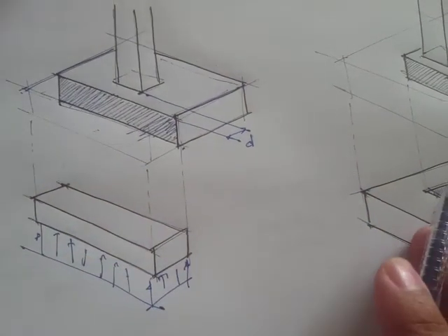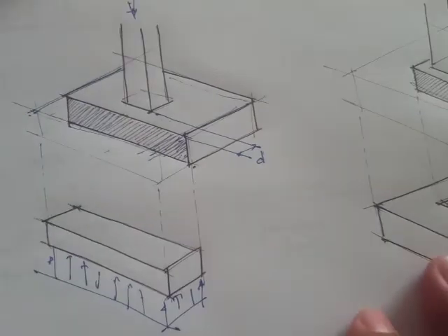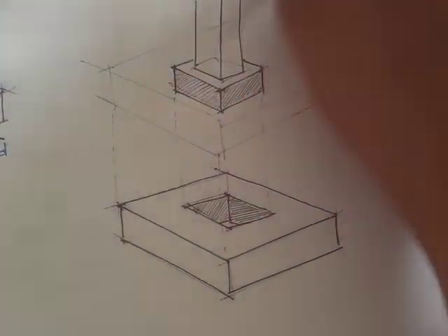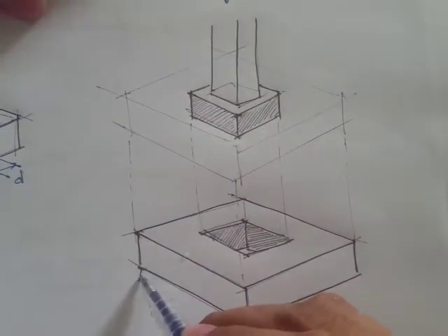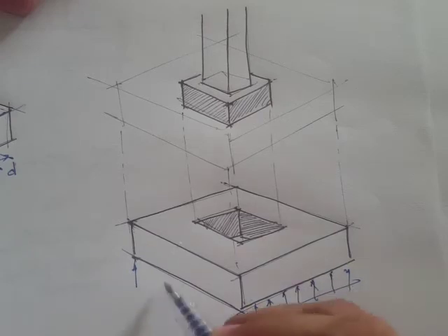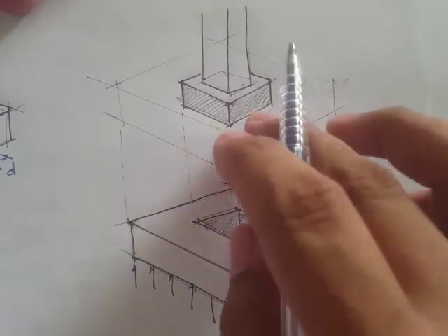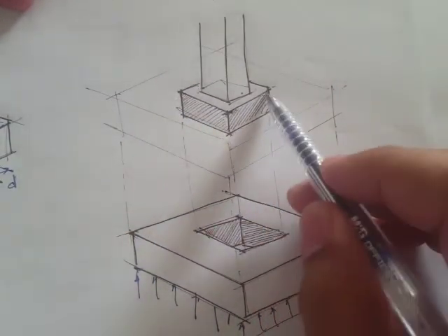Now, for now, let's just focus on the shear forces in footings. So this is the one-way shear. Another one is the punching shear or the two-way shear. Because you have loads here and you also have loadings at the bottom, it is possible that the footing will fail in a manner that the column actually punches, or it separates, it breaks at this critical section.